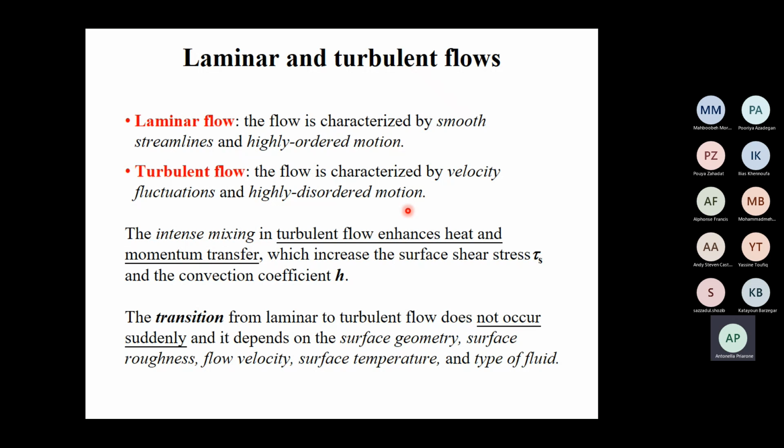Obviously, the turbulent flow, so the creation of eddies, enhances the mixing and so enhances the heat transfer rate. The h coefficient by convection is bigger for turbulent flow with respect to laminar flow. But by enhancing the mixing and the heat transfer rate, I increase also the momentum transfer, and I increase also the losses by friction.